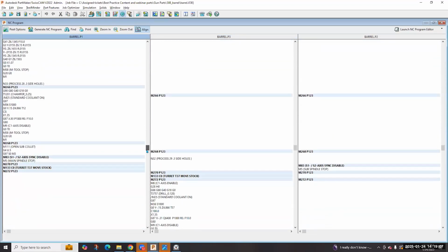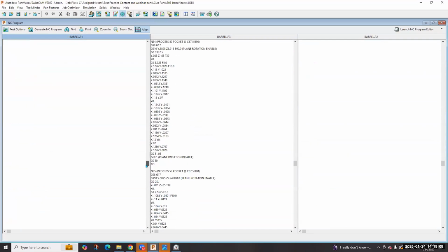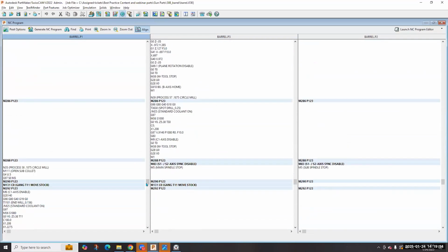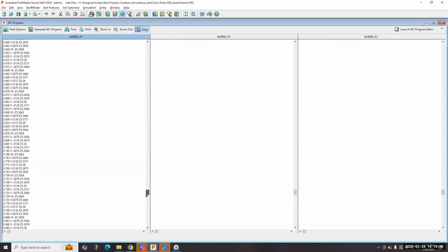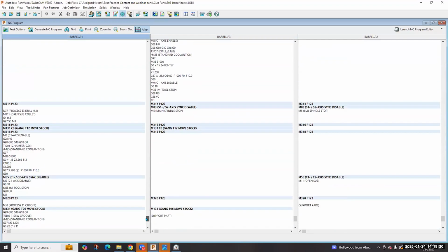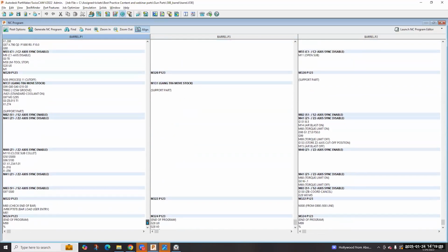I'm just going to scroll down to the cutoff because that's really where the rest of the majority of the wait codes are. But you can see a lot of wait codes to go back and forth between those tool posts. Okay, let's see. Okay, cutoff.